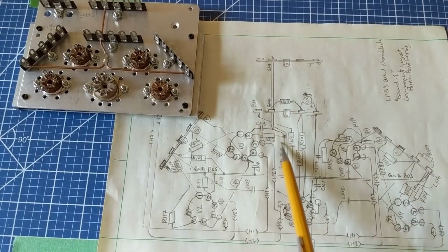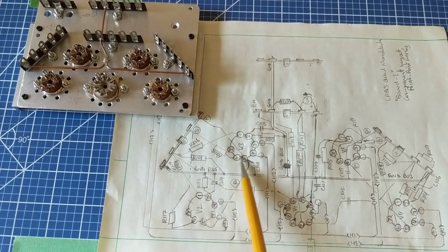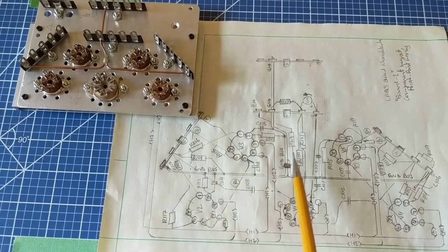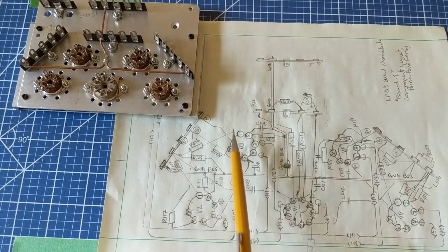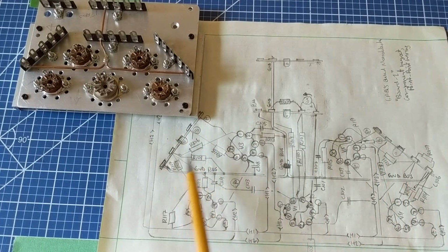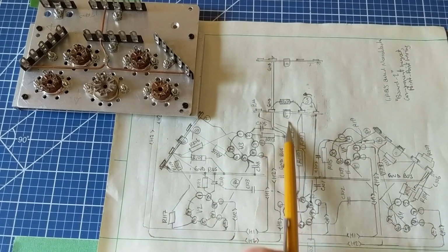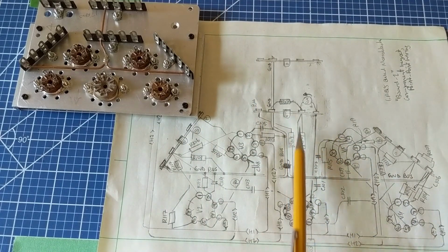So you can see here the ground wire, this from the star point, and then all the resistors and capacitors from the circuit. I determine where they're going to be laid out on the point-to-point wiring, so I have a pretty good idea of how to actually wire the circuit. And this gives me an idea of if I have enough tie points or not, if I'm going to be running into any problems with long lead lengths for components. This is somewhat exaggerated. You can see it's much shorter here, so I don't think this will be a problem for the resistors to stretch.